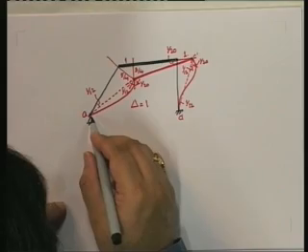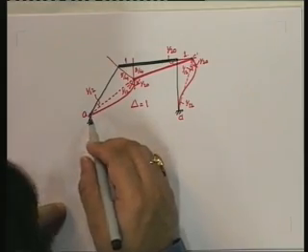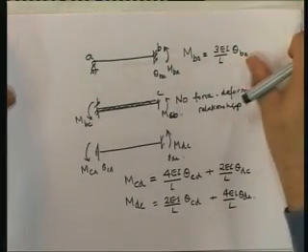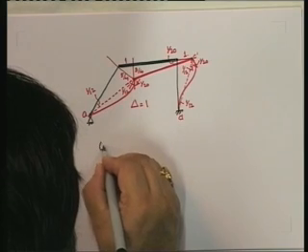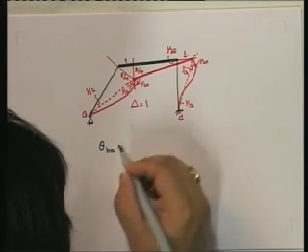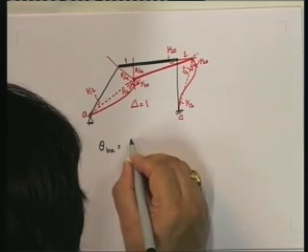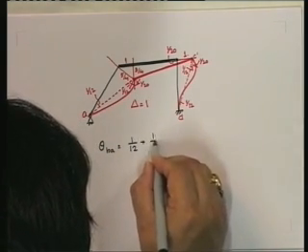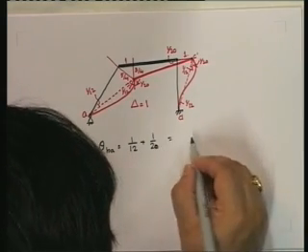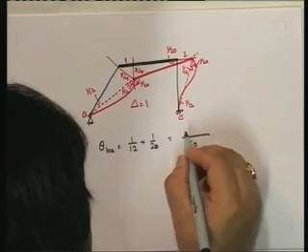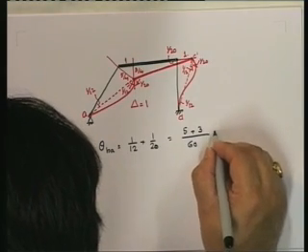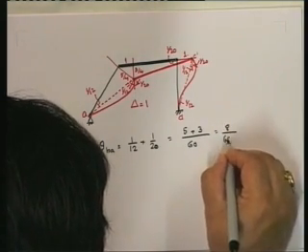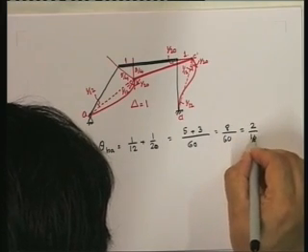So theta AB we are not interested in because again remember that in member AB, the only member in different relationship is MBA equal to theta BA. So keeping that in mind, we only need to know what theta BA is. So theta BA is 1 by 12 plus 1 over 20. So this is equal to, in terms of 60, 5 plus 3 is equal to 8 upon 60, which is equal to 2 upon 15.